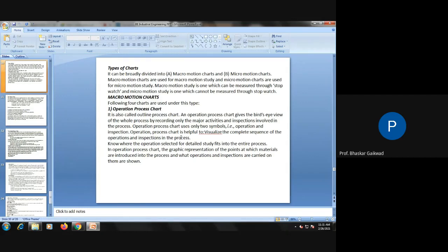If we do manual inspection for the process, a lot of time will be wasted. And you know that in industry, downtime is very critical and very costly. So you have to reduce this downtime. Manual inspection is expected to be replaced by non-contact inspection, automatic gauging systems, or sampling methods.